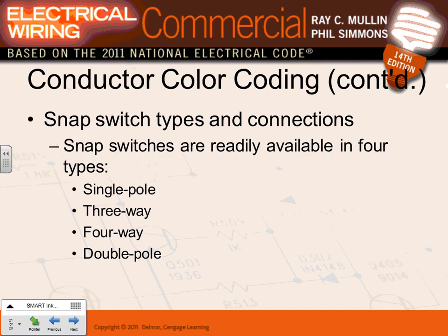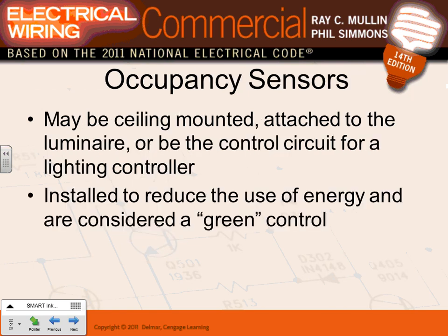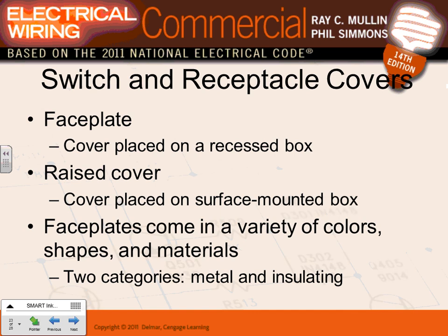You can get switches, guys, in the following formation. You have single pole, three-way, four-way, and double pole switches. We talked about this one before. Occupancy sensors, that's a new topic for you. An occupancy sensor is an electronic device that senses motion and triggers a little contact to open or close based on the setting and turn a light on and off. Cool? That's what you guys are going to be doing with us. The occupancy sensor acts as a switch. We'll look at a couple of them in a second.